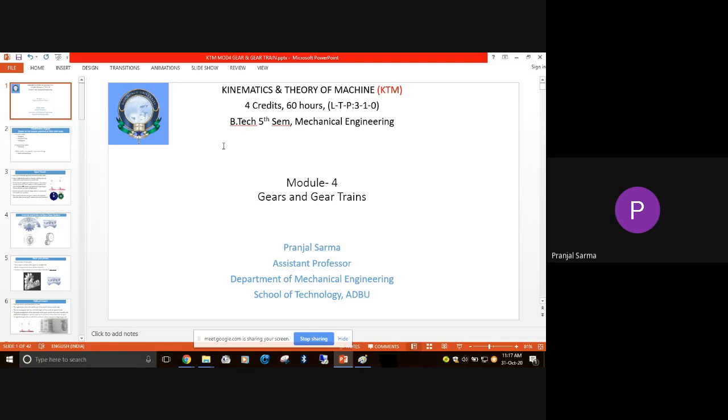Similarly, when we talk of two gears in mesh, if nothing is mentioned, generally the bigger wheel is considered the gear. By the word wheel we mean gear only. Sometimes we use the word gear blank to indicate the gear. The gear blank is the piece on which we cut the gear teeth, so from the gear blank we manufacture the gears. The friction wheel or circular diagram we draw to indicate gears without showing the teeth can be considered a gear blank.